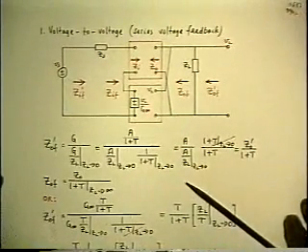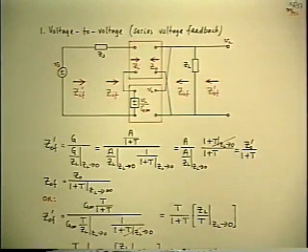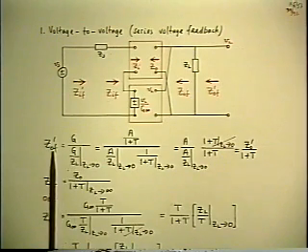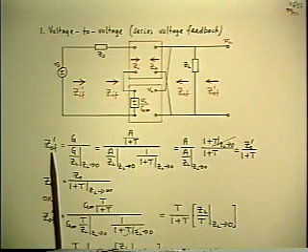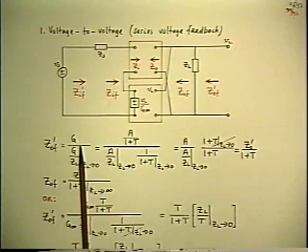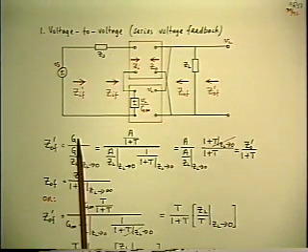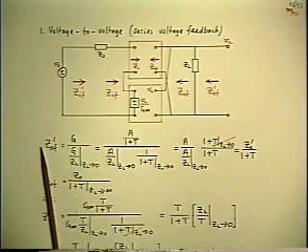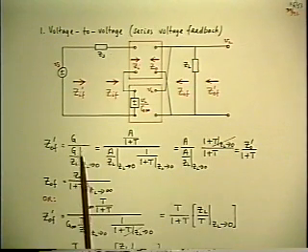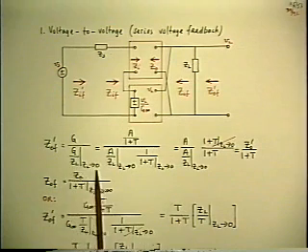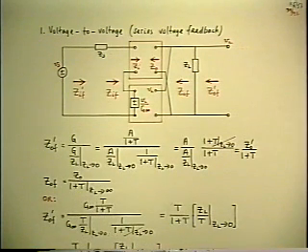Okay, here's the derivation. All we have to do is use the output impedance theorem that says the outside output impedance, closed loop, can be found by using the theorem where the gain is the closed loop gain of the system. So here's the output impedance theorem we've set up already, and you apply it to the G. So the numerator is just the G itself. The denominator is G over ZL as ZL goes to 0, which of course is really just saying open circuit voltage over short circuit current.